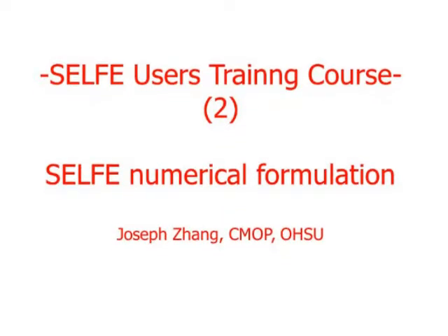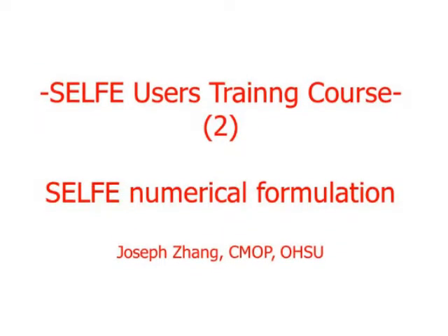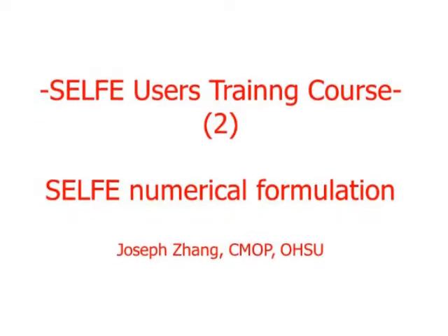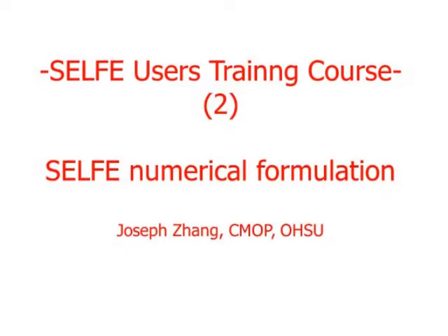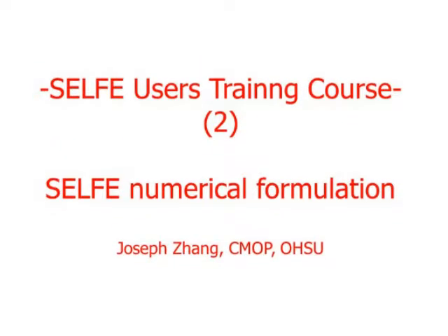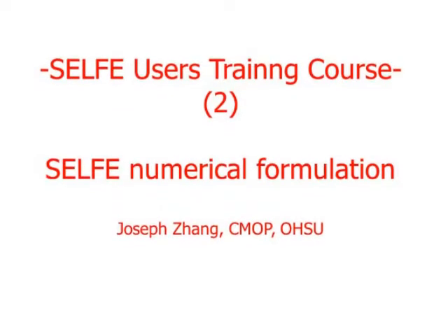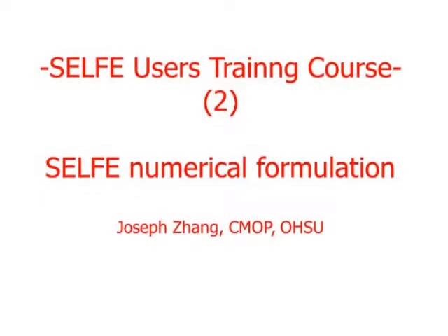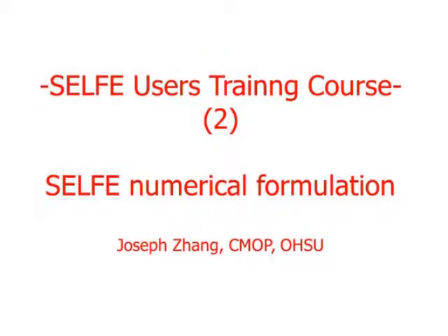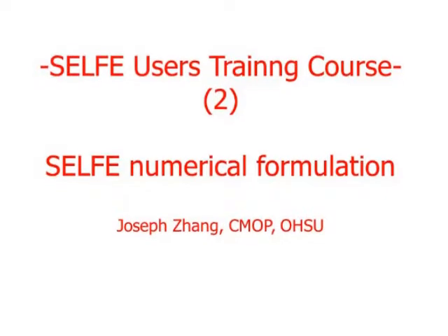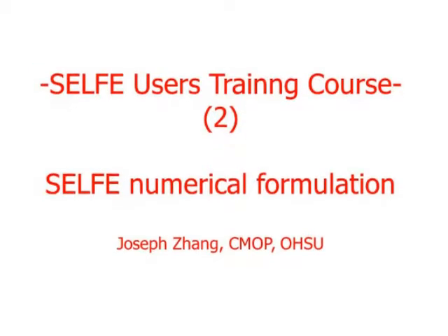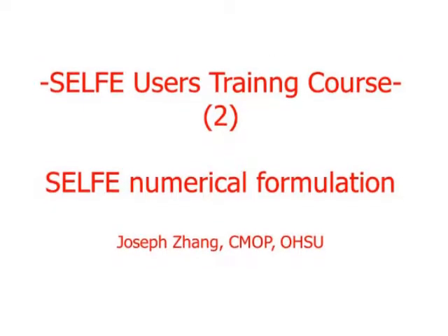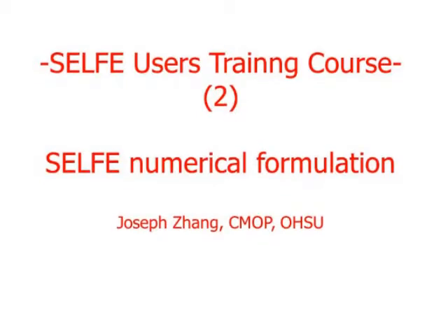So lastly, I'm sure most of you are familiar with this idea of upwind for solving advection diffusion equations. Upwind is actually a method to treat the advection term. If you look at this equation, which is a discretized pure advection equation, u is the advective velocity. You can see that the first derivative is discretized in the upwind direction, depending on which way the signal comes from.